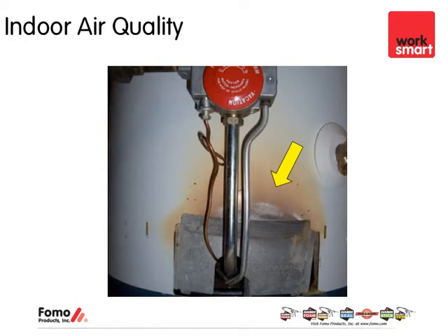What's happening here is, imagine a house is being depressurized due to the stack effect. This hot water tank is most likely down in the basement of the house, and the air is infiltrating from the basement and exfiltrating out of the attic, and that air movement is forcing the air from the basement to move up into the interior of the house. As a result, that depressurization is pulling the flame, the combustion flame if you will, of this hot water tank out, and that's why you see charring on the outside.